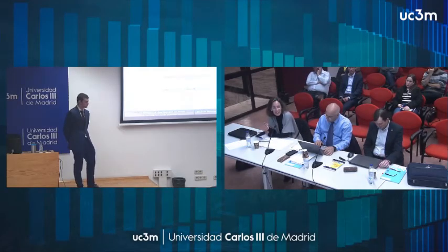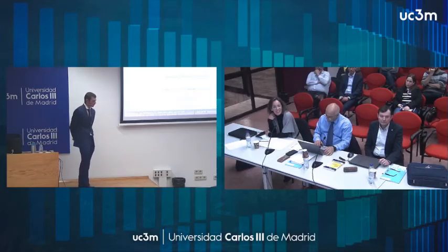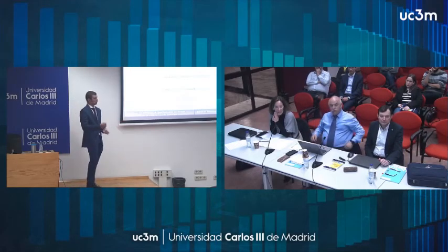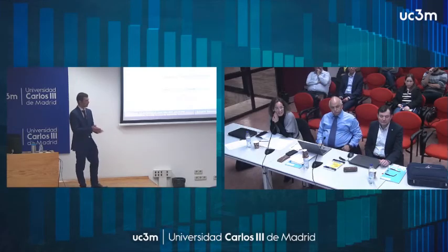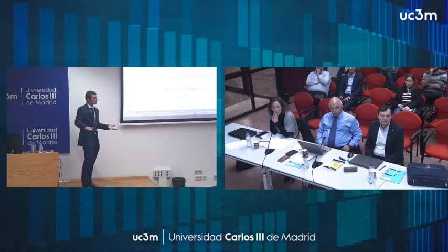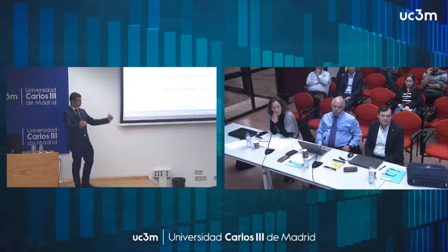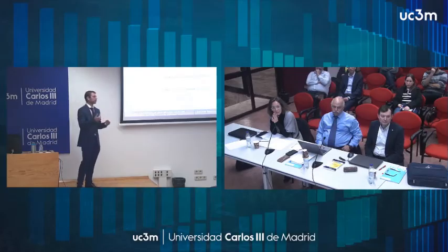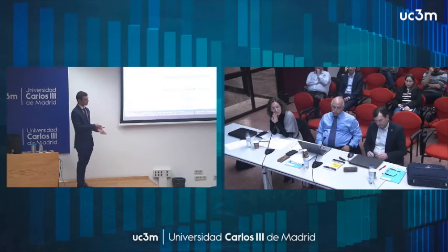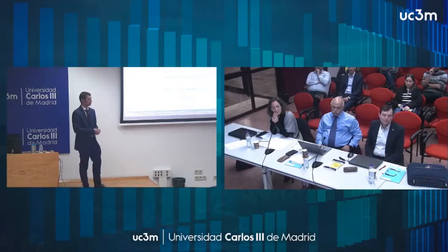So why haven't you used your simulation program? Because the SolTrace results are more accurate. My simulation program gives some rough first approach results. And also because my program does not tell me the heat flux of the different solar stages, the flux map. What I did in SolTrace was only to consider, for example, all of the primary mirrors, and only focus on the heat flux that reaches these primary mirrors, and afterwards the same, but with the beam down reflector, discretizing and focusing on these different sections. I couldn't have done it in my prototype or in my design methodology.